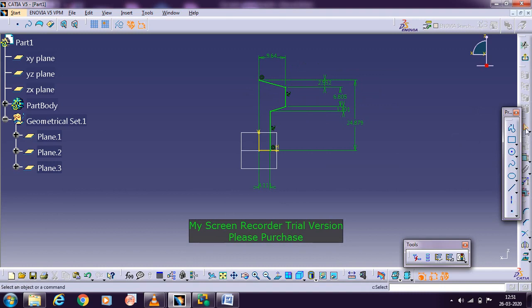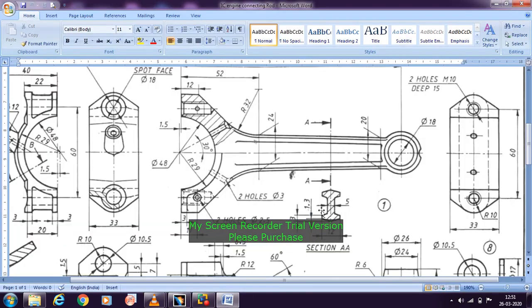Now you need to change the dimensions. When you see the sketch here, the total height is not given for this slant measurement, but it is given only for these two shapes or lines. The total thickness is 3 mm, given for the outer portion. For the outer portion it is given as 1.3 here, and for the inside it is 3 minus 1.3, which gives 1.7 inside.